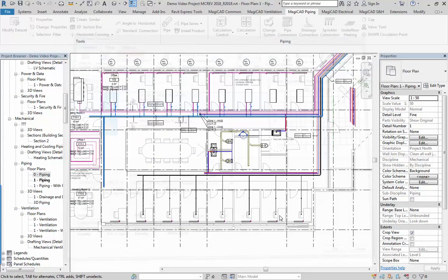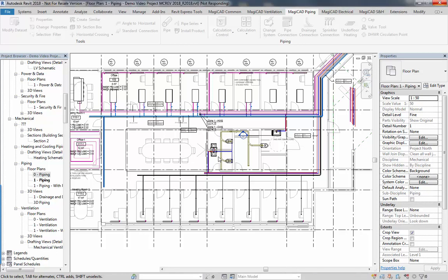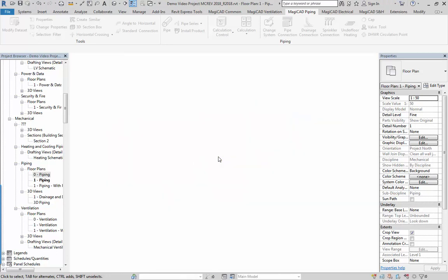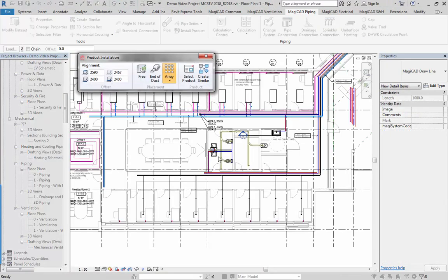If you're happy with that product, press OK. What it'll do is convert the product from the cloud into a Revit family and then insert it into the project with those technical conditions preset into it, so you can start putting those items into the project with the pipe connected up, and then you can do the calculations as we showed in the previous calculation part of this video.